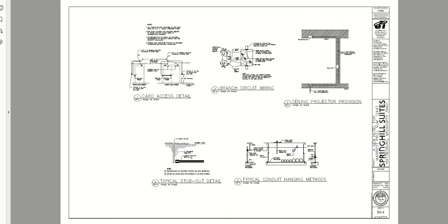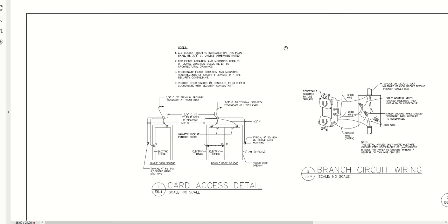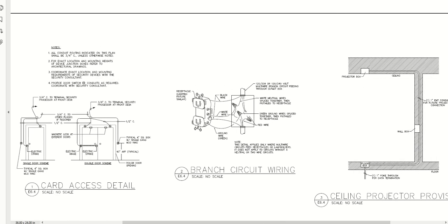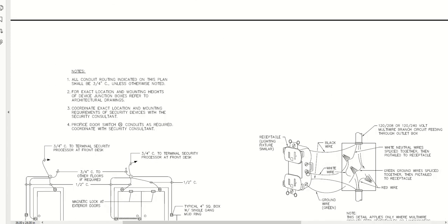How we wire up our outlets. One thing that's important here that we're showing is most of these outlets will have 2 connections here, for if you want to have, for some reason, a different neutral connection to one outlet than the other, but then they put this little strap across it. What some people would do is run the neutral down here and then connect it and run it onto the next outlet. We want to make sure you don't do that, that you wire nut this here and use that to run to the next outlet, and just run this pigtail, is what we call this, to the power outlet here.